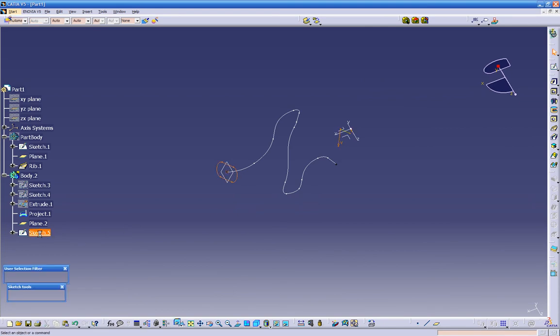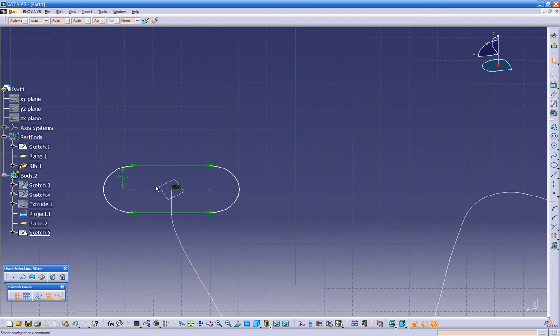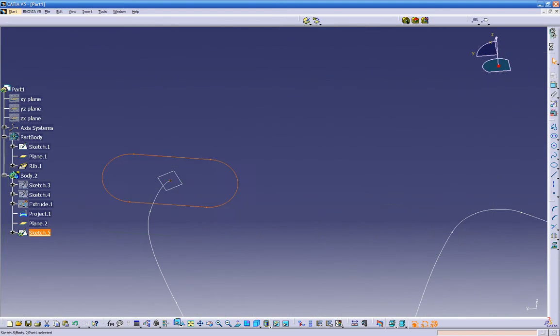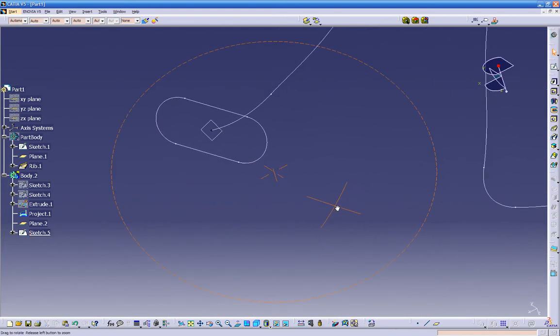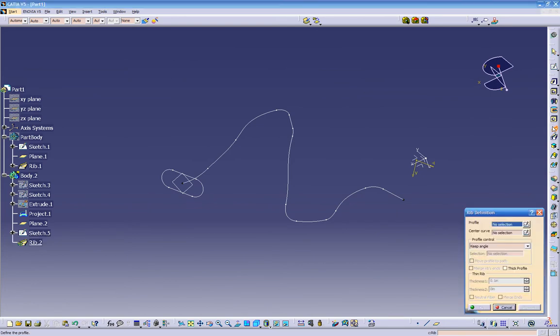Let's go back into our sketch, and I guess our point, see this is, I don't know how come I didn't pay attention, but this is not on. So my point in here is not set for the construction element. So just click on this. Now once I get out of the sketch, we don't see our point anymore. So now we can go back to the rib option, and we shouldn't get the error anymore. Click on the profile. Now click on the center curve.